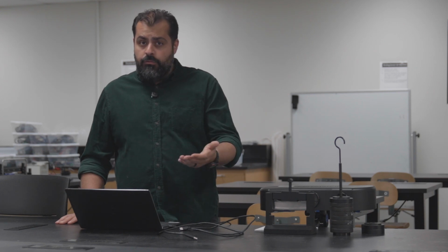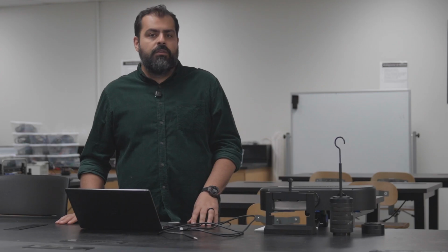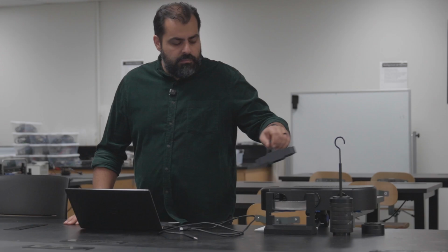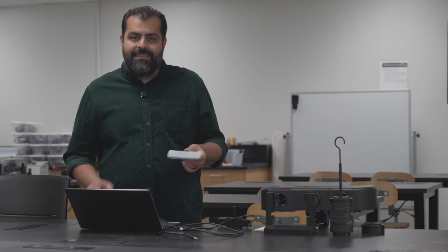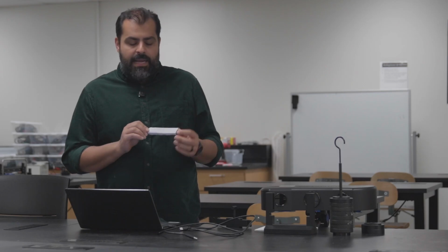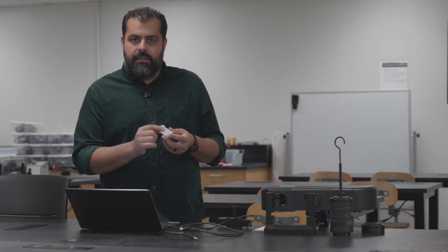Well, there are a couple of preparations you need to make to your sample and to your device itself before being able to measure the strain in the field, right? And we have the sample right here. We have to make sure that it has a pattern on it. It's called the speckle pattern. So we usually use a white background and we usually create small dots on it.